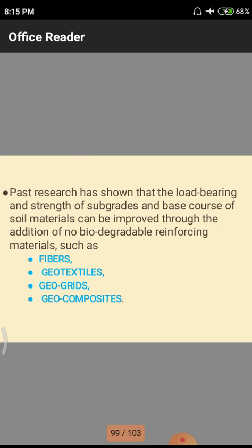Likewise, the strength of the subgrade. Normally, whenever we construct a road, we use rollers for densifying the soils and subgrades of the roads, so that we obtain the strength of the subgrade when there is no void content and no entrainment of water.